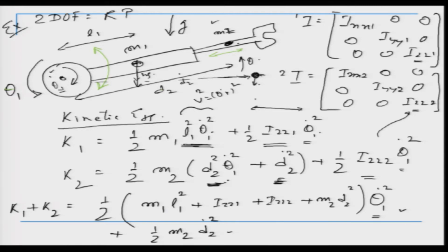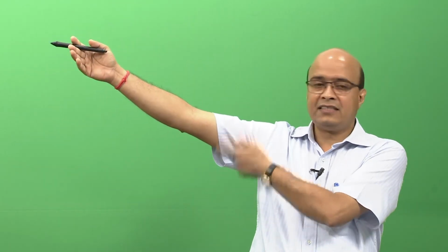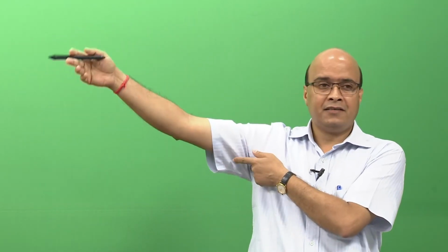So, let me explain the concept of the 0 reference again. If you have an arm like this and I say this is my 0 reference, whatever is going up is my angle theta. So, its sin theta is the height there, but this is actually not 0, because if it has some potential energy here, what this means is that if I switch off the actuators, the arm will immediately fall down. Why? Because gravity is acting in the downward direction.